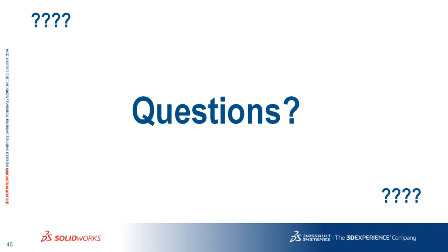Any questions? Go ahead. If your company started out using create a part for every different configuration, and you change that setting to create configurations, what happens to all those files, or what are the ramifications? Well, the toolbox will still maintain those parts, but you're still going to have to replace those eventually with the one that has all the configurations in it. If it's legacy data, it should be fine just to leave it. So any new part created will be a file with configurations? Correct. And it's fine to leave them in your copied parts folder, whatever you're doing with them.